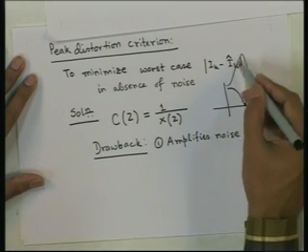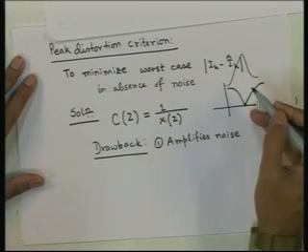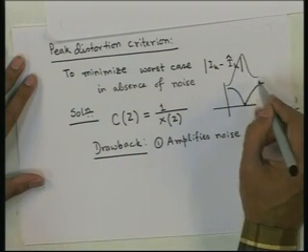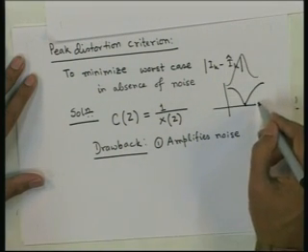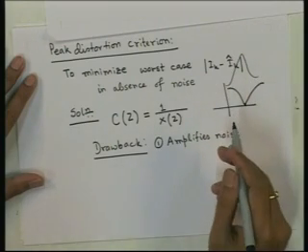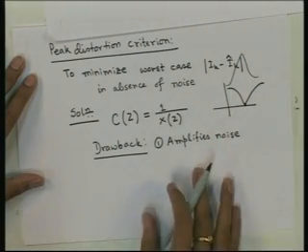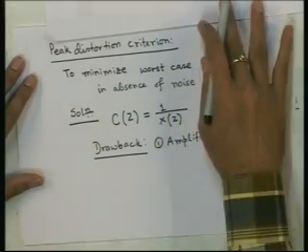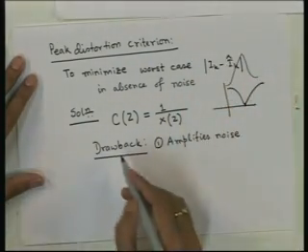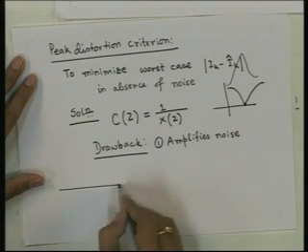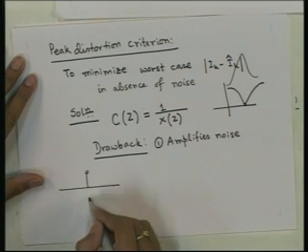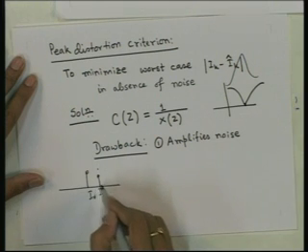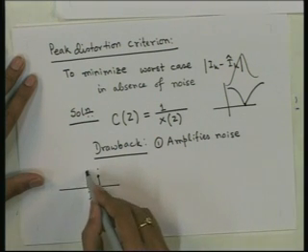And too much amplification of the noise in some bands actually creates a problem, because the overall noise itself increases because of that. So, it amplifies noise, otherwise it cancels ISI completely. So, the contribution of neighboring symbols: if you plot I naught here, this is I naught, this is let us say I 1 and so on, at the output of it you get this plus some noise.